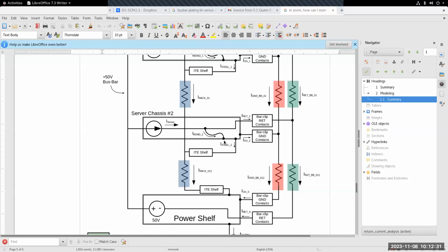The other question I have is related to the expected value of the earth ground current. When you look at these AC three-phase systems, the expectation is that you could have up to a 30% phase imbalance. That's how you get your earth ground return. So I would say that's probably one target you could expect. That's the neutral line, though. That wouldn't be the earth ground.